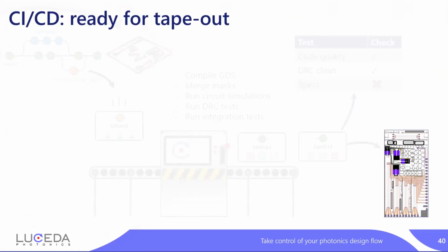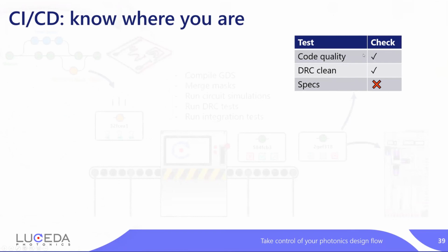So here, if you think of a test report, it's of course up to the user, depending on the project you're working in, to set up a series of tests which will help you get to target or get your specifications. It can be that the insertion loss has to be smaller than a certain number and so forth, and you can add them as specifications. And also, if you then run Monte Carlo simulations, you can do some kind of analysis on that and have that as part of your test suite. And again, this can help you to cope to some extent with this variability. So if you make a change in your design and suddenly you see some of the specs start failing, it could be because of that variability.